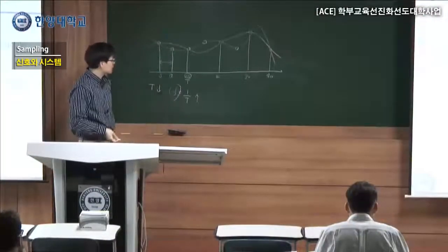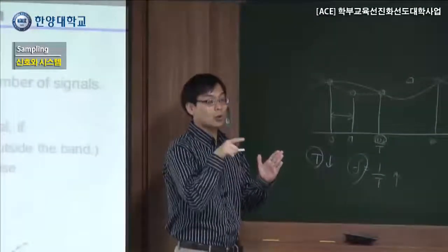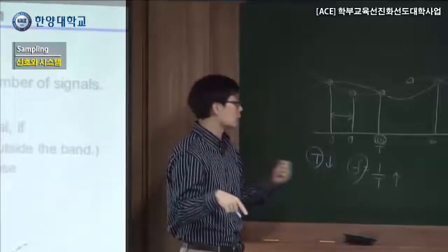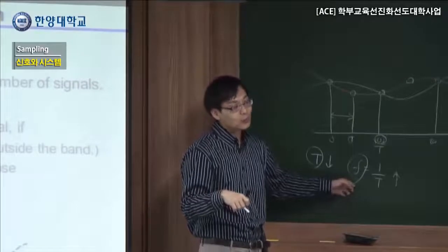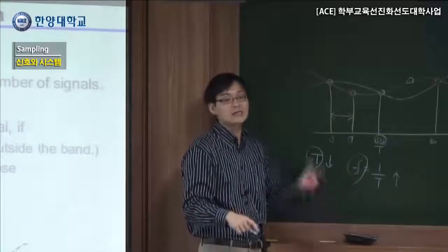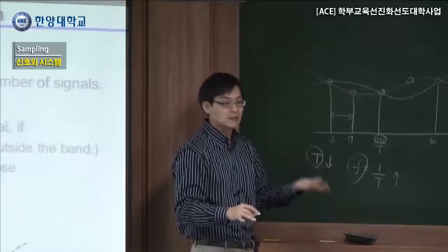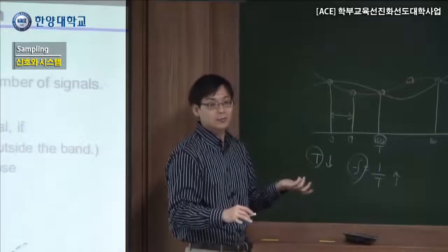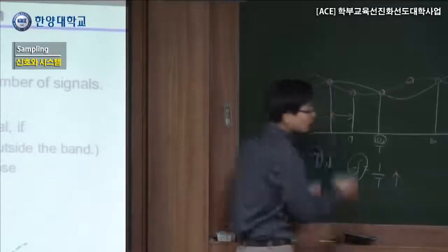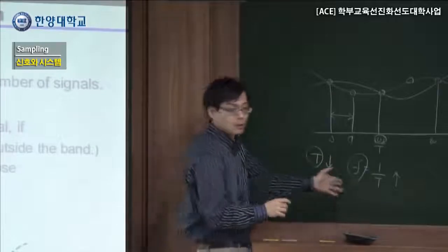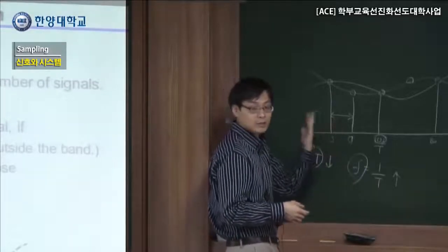So this frequency is the pair related with the time interval of when we are sampling, right? So this one is called the sampling frequency. Frequency should be at least 2 times larger than the signal's frequency. That's a basic rule called Nyquist theorem, which we talk about a few pages later. So keep in mind, we have to increase the frequency. If frequency is not enough, then we cannot have the original data.